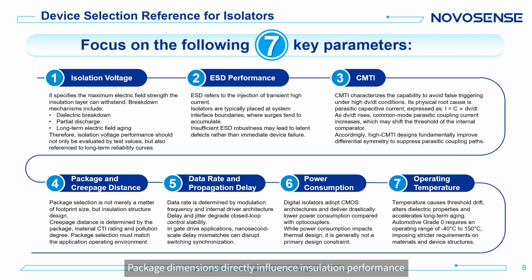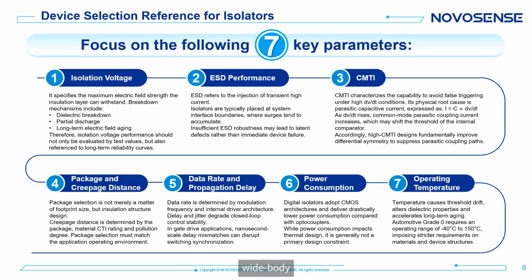Package dimensions directly influence insulation performance. Although miniaturization offers many advantages, higher isolation voltage requirements generally demand wider packages. For this reason, NOVOSENSE provides standard body, wide body, and extra wide body packages.